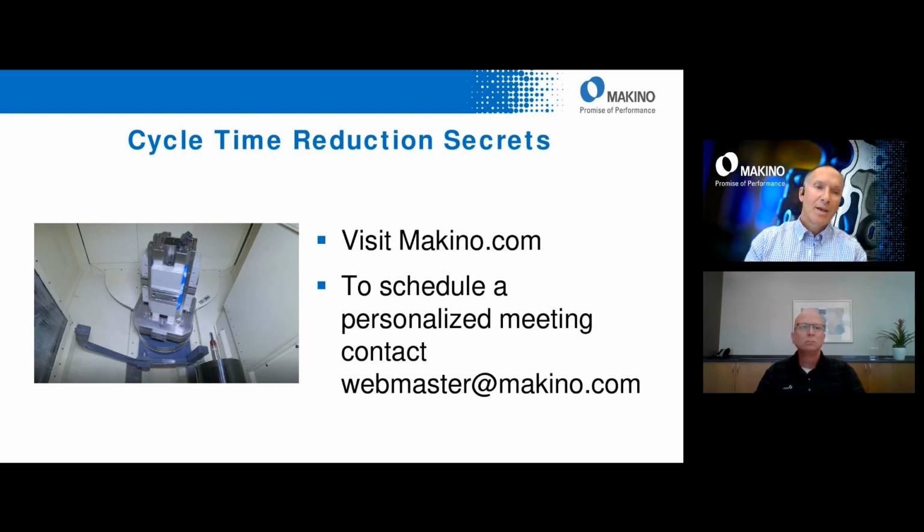Okay. And here's a question from Gregory. He's asking about a laser tool check. He wants to confirm if he should be programming after that. So referring to an NC4 Renishaw laser, I assume. So run it through the laser, do your tool breakage detection in the work zone with that particular option on the machine. You can use M319 right after that as well.